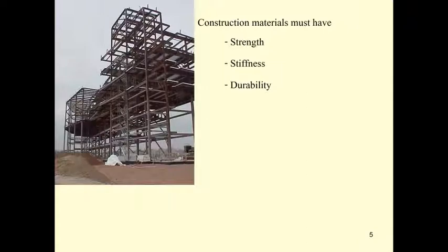Anyway, when you build a structure, small or tall or big or very large, you're going to consider three things. The material that you use in the building must have enough strength. It won't produce any crack under the force, won't cause yielding under the loading. Just strong enough. And the deflection of the material used to build the structural member is supposed to be very small. Large deformation causes the structure to lose its function, and also sometimes causes very high vibration. So the building seems unsafe for the people.